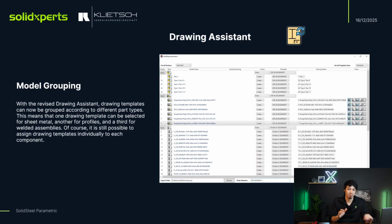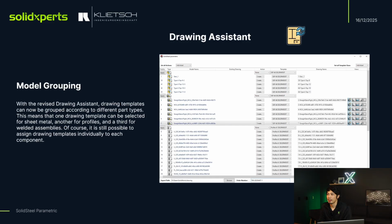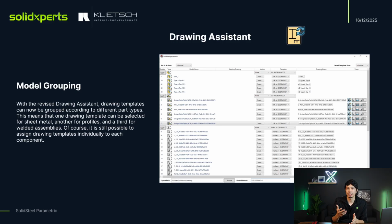That's super nice, but what about drawings? All of my exports, right? This next enhancement actually allows for model grouping when you're creating your drawings. So what does this mean? It's going to create different sections for your different part types. Imagine you have some sheet metal parts, you have some full profiles, and then you might have some welded assemblies, for example. Obviously, you can still manually assign the templates that are being used to generate these different drawings, but grouping does definitely make your batch drawing creation much more efficient.